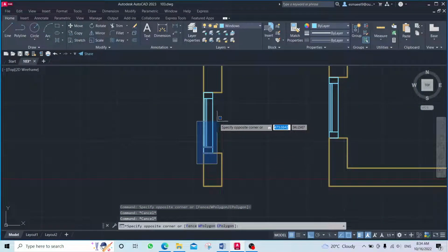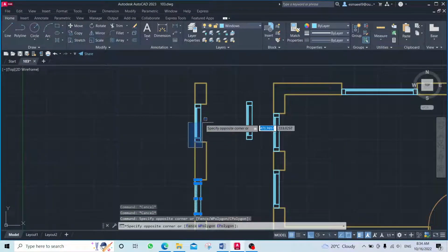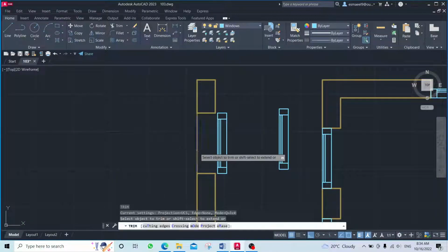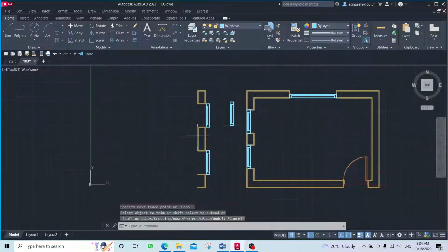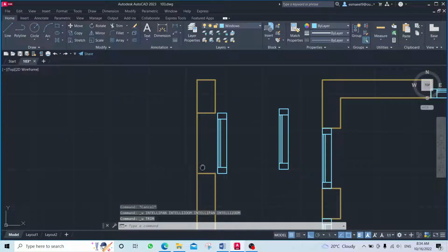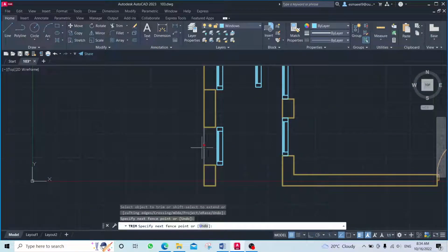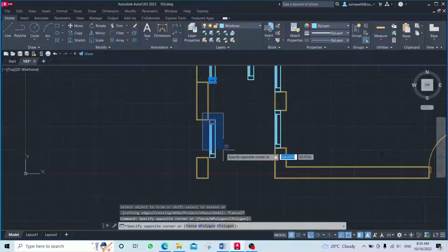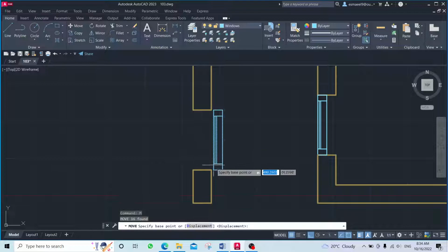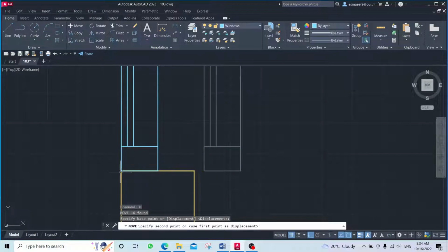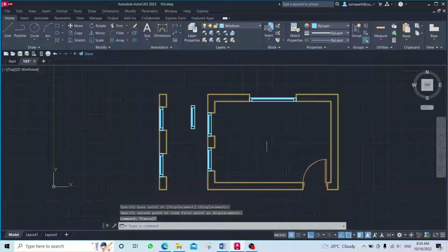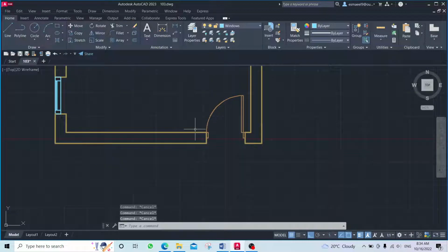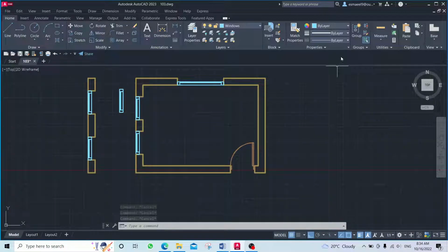What I'm gonna do in this case: select these two, move them from any point to any point, TR. I should make this point before, Control Z, TR, and delete this one. Now select these two windows, this one and this one, and click move from this point into this point. We do have the wall. The same thing with the door. We even explained how to make a wall from the previous picture.